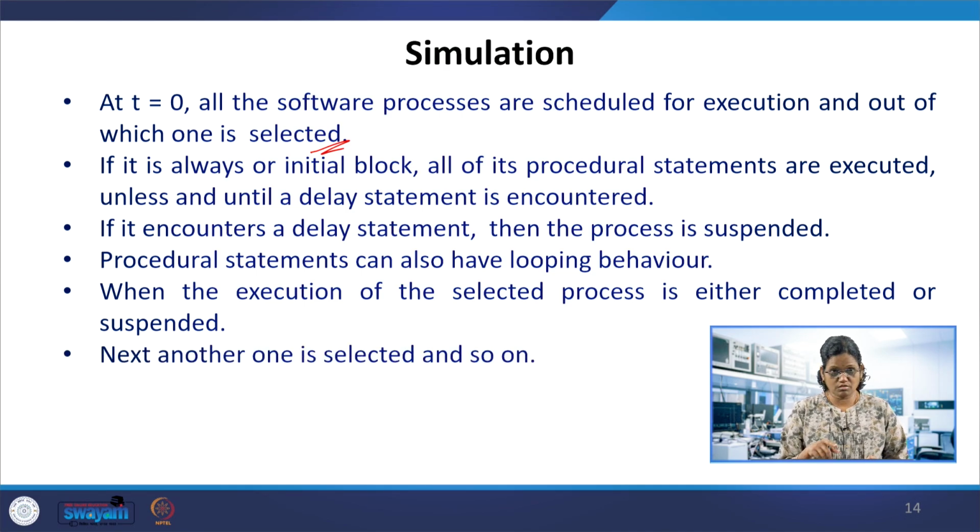Next in the event list, the next process, the next module, the next concurrent statement is selected, and the same way it is executed, and so on. So every concurrent statement deserves a software process, and those processes are executed one by one. This continues for all the processes, and then the simulation stops or completes.